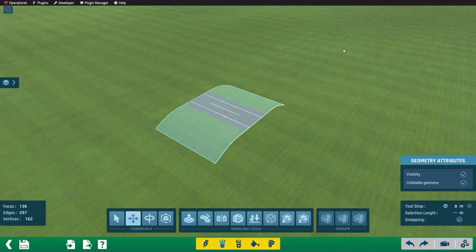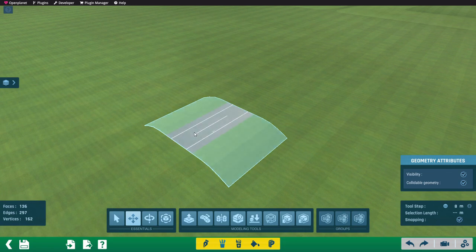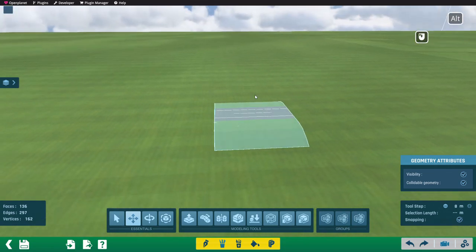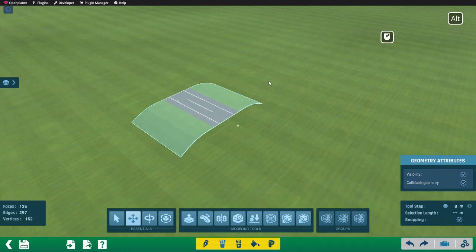Number 6. An item set off-grid. The sixth and last method I suggest is to make an item set with items not on the grid but connected with pivot positions in the item editor. The idea is to make 15 degrees angle turns and use the plus and minus buttons in the main editor to rotate the items by 15 degrees, and to use snapping to connect the items.